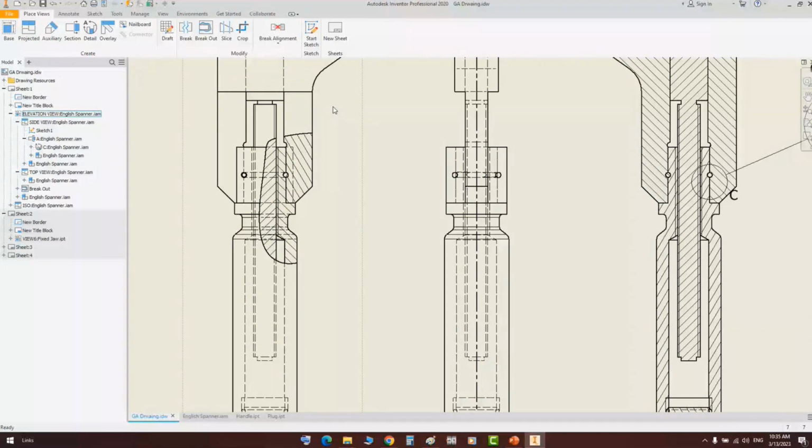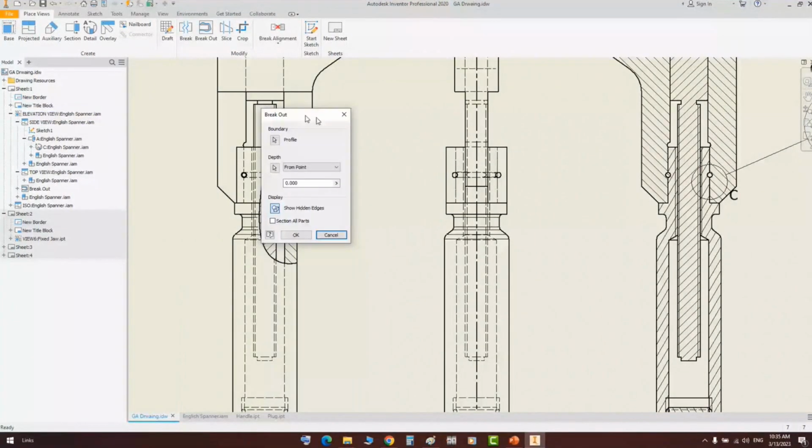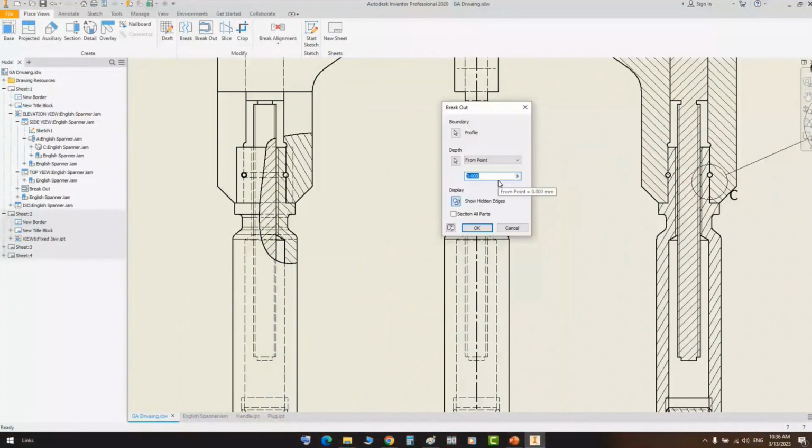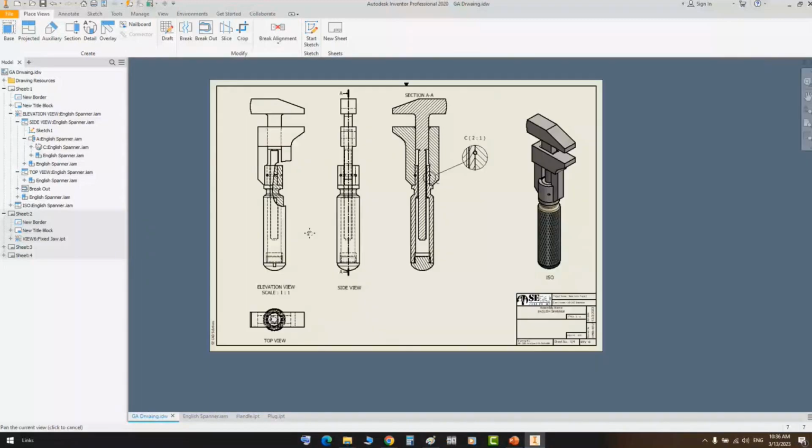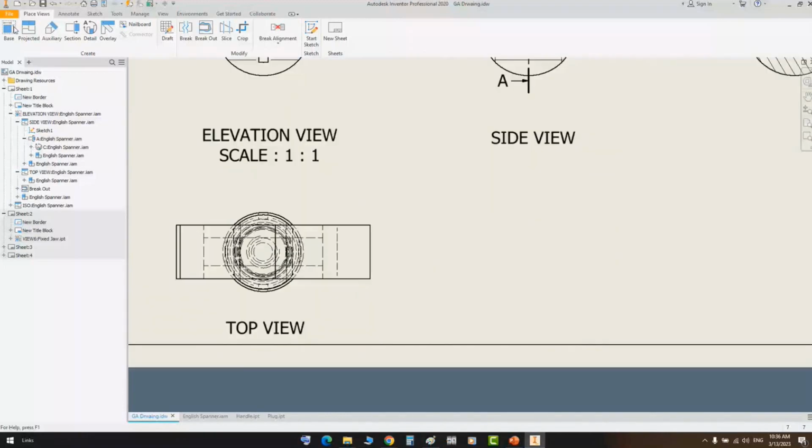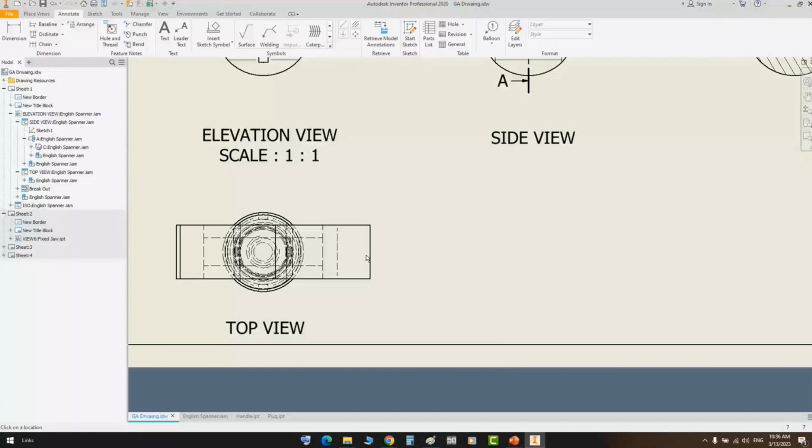Again, for this, you can define the depth. So if we make this one 10 millimeters, you can see that we make the depth here. That's the center. So if we make a line here with the center, we select the center point at the middle.